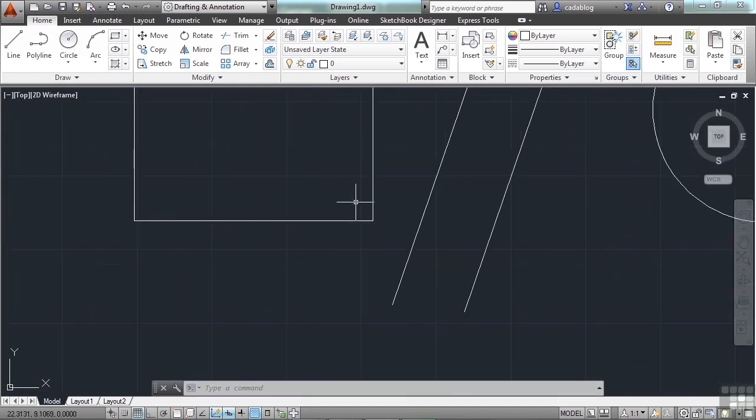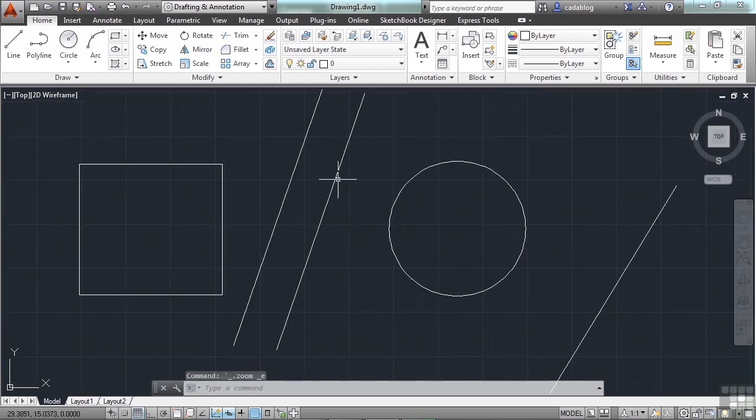That's very handy. One other trick that you can use with your scroll wheel is to double click it. That does a zoom extents. We'll talk more about what zoom extents is and a lot of different ways and how you can use the zoom command in another section. But the zoom extents will zoom all the way out to display the extents of your drawing line work in your workspace area, which is very nice. That's a great way to navigate in your file or in your drawing very easily and very quickly.